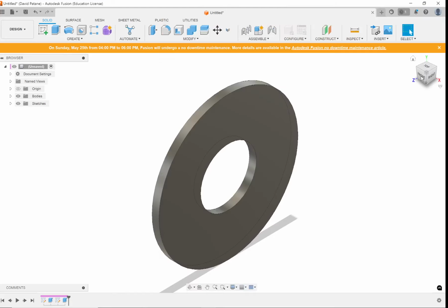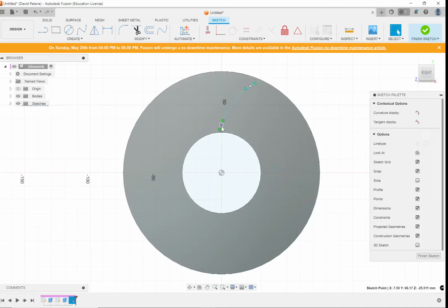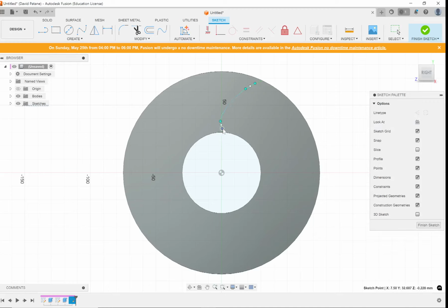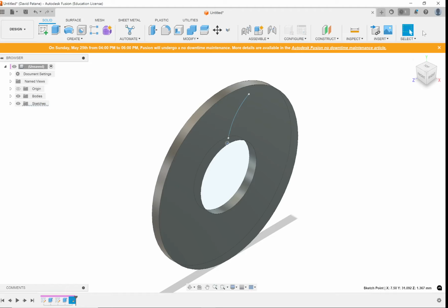So for us to do this, we'll show you how a fast CAD person would do it. We can sketch on this surface. We know our holes are going to be here. Our holes have some sort of curvature. Let's say they go like this. Press my enter button, and now what I'm doing here is I want to make the curve that these particular holes will follow. All right, so this is the curve that I want those 4 holes we had there to be along.